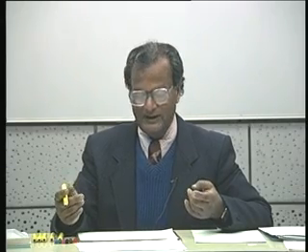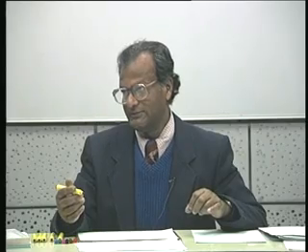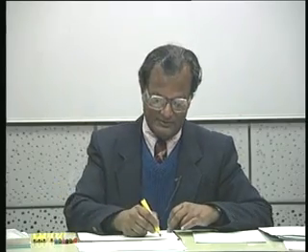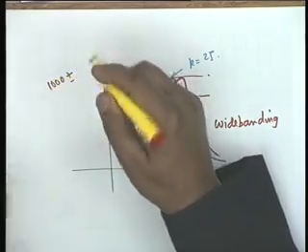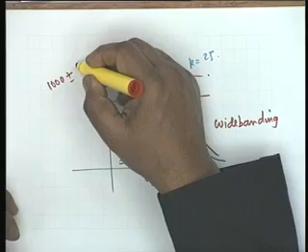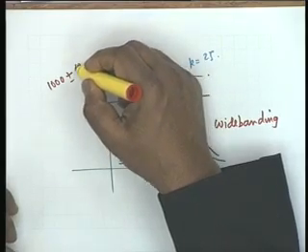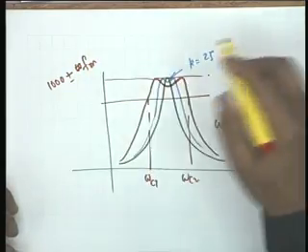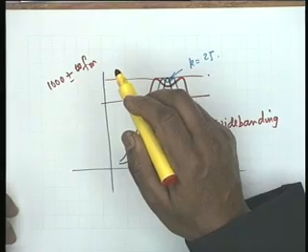But 1000 kilohertz is not 1000 kilohertz. It is modulated by music, speech, whatever you want to transmit, and therefore there is a certain non-zero bandwidth. If you take the Fourier transform of what you receive, the actual spectrum would be 1000 plus minus FM, where FM is the maximum modulating frequency.